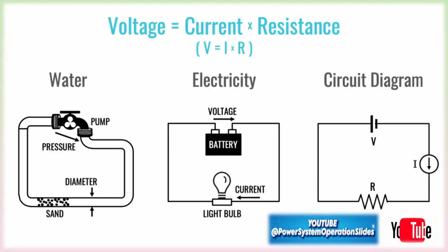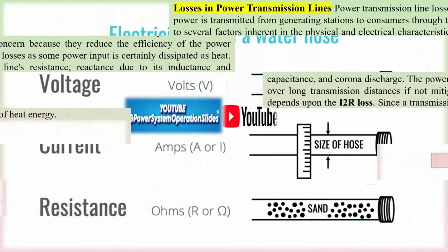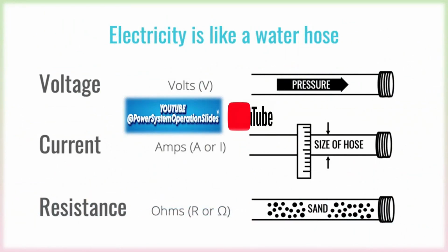1–2% of energy is lost during the step-up transformer from when the electricity is generated to when it is transmitted. 2–4% of energy is lost in the transmission lines. 1–2% of energy is lost during the step-down transformer from the transmission line to distribution. 4–6% of energy is lost during the distribution, so the average loss of power between the power plant and consumers ranges between 8–15%. In modern society, we cannot think to live without electrical power.